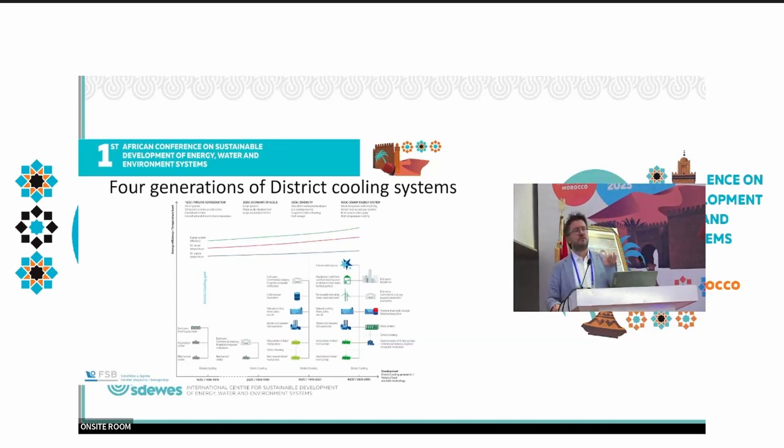In the fourth generation, the key issue is that you have heating demand and cooling demand at the same time. Of course, you can have a separate chiller and heat pump working in parallel. So using heat surpluses obtained from cooling for covering different kinds of heating demands, and surpluses from heating can come and satisfy certain parts of the cooling demands.